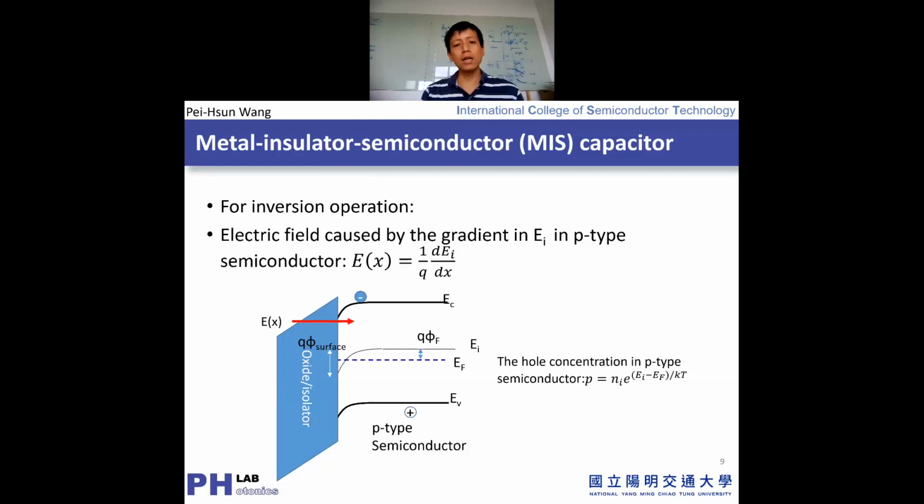So you want to accumulate the electron from the bulk material. So it will be a long distance and really far away, a time-consuming accumulation process. However, if you change your voltage really fast and you want to change the potential and change the electron, if this frequency is high, maybe several megahertz, it is hard to modulate your channel because you need to wait for the electron moving from the bulk material to the surface. So there's the time dependency.